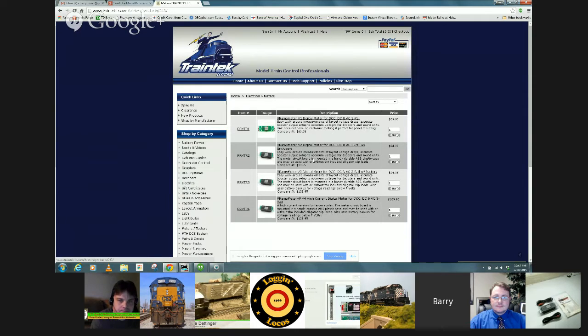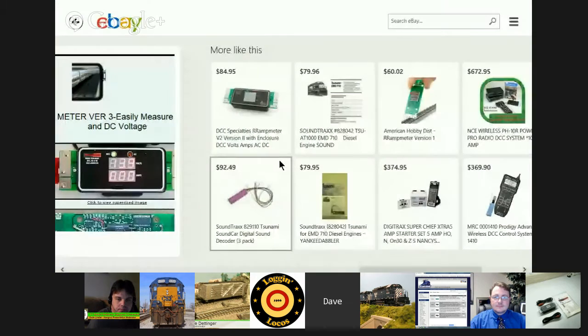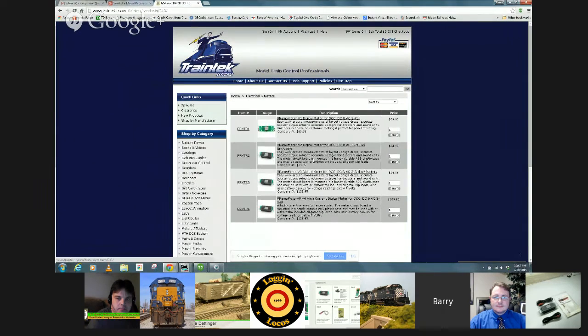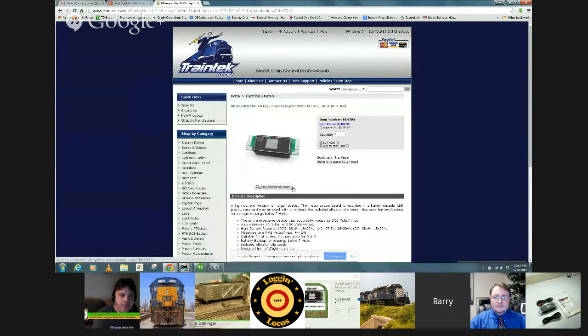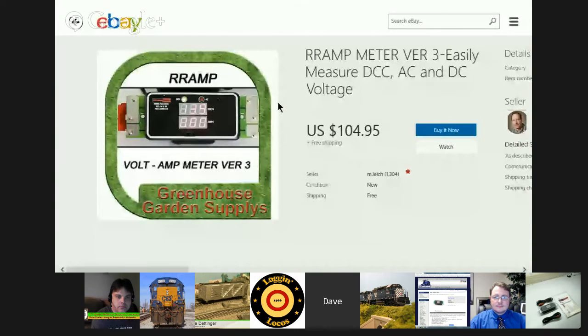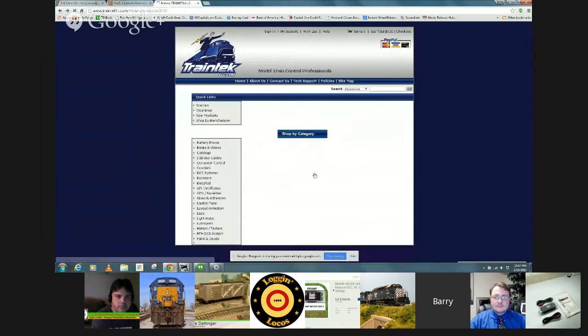So it probably uses the battery to power itself, whereas with version 2, if the track voltage is not high enough, it won't work. Then there's a version 4, which has battery backup, but it's designed for high current applications. Let's see what the current specs are on that one. That can go up to 20 amps. 20 amps. Yeah, that's ridiculous. That's for G-scale guys.